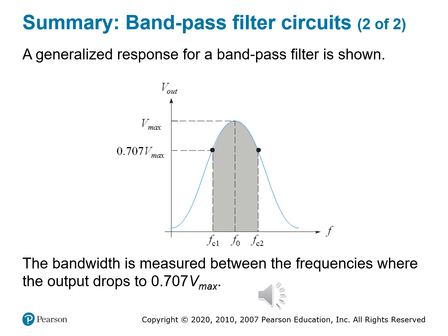The engineering implication is that the bandwidth tells us how selective your filter is. If you have a narrow bandwidth, your circuit is sharply focused. It's great for precision, like a radio tuner. If you have a wide bandwidth, more signals get through. It's useful in audio applications or broadband systems.